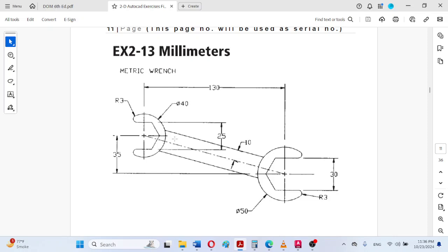Students often get confused and mistakenly think that this hexagon is inside this circle, so that this is an inscribed type of polygon. This is never the case, because this circle is actually independent and it has no connection with this hexagonal jaw or shape. This hexagon will be specified or described by an invisible circle which physically will not be shown or drawn. That will only be specifying the size of this polygon.